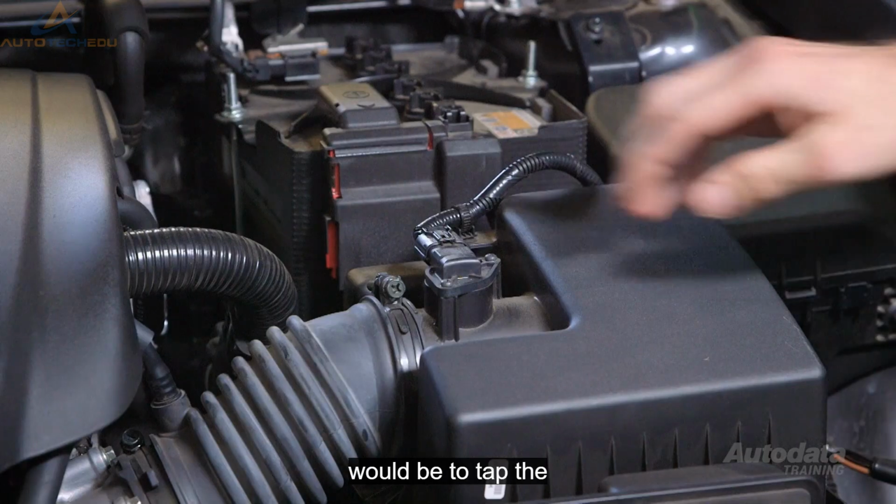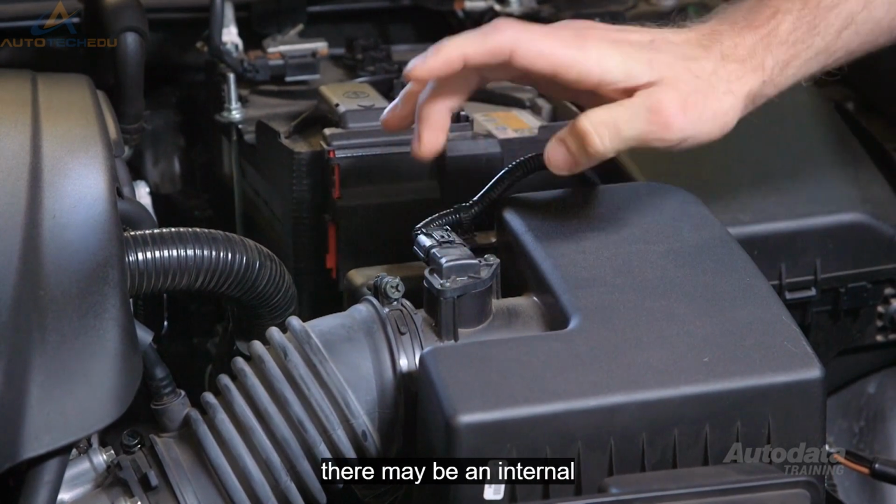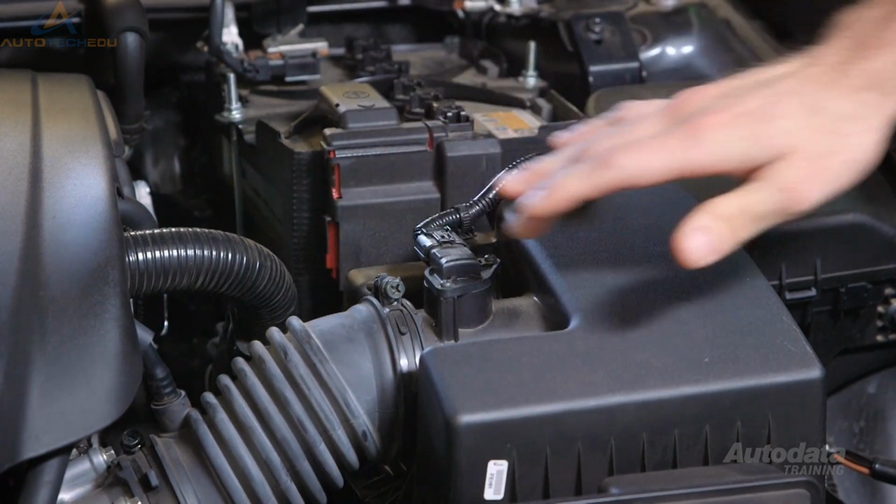One test would be to tap the sensor while watching the data. If there is a noticeable change, there may be an internal fault with the MAP sensor.